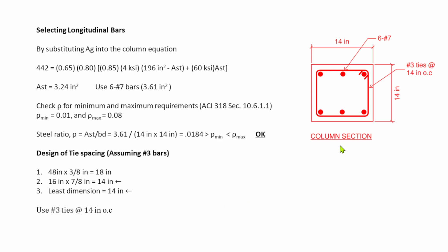But some other engineers at the site use 12 inches, which is a very common spacing, or 8 inches. So it depends on engineering judgment for column spacing, because some companies have their own standard of spacing, although the requirement is 14 inches. As per calculation, sometimes they use 12.